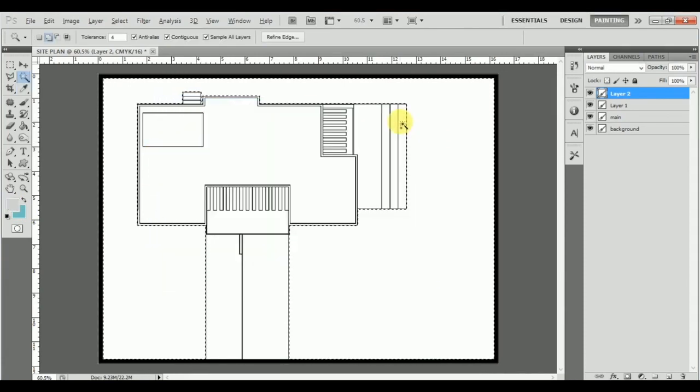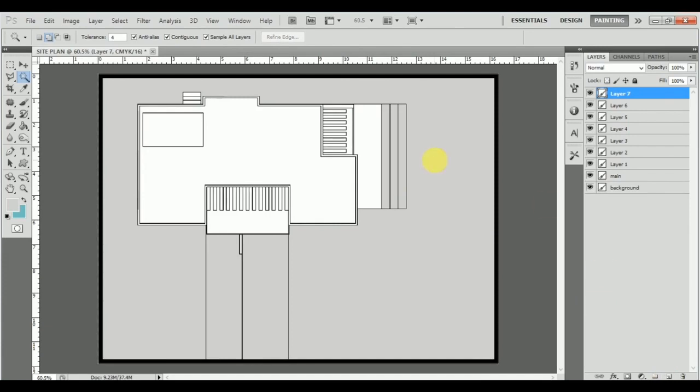Now similarly, like we have created layers in the past, we'll be doing the same thing over here. Each and every particular space will be created and given a layer. We'll also start from the bottommost stair over here, because those two will be in separate layers like this. So we quickly go ahead and fill all these layers up. I hope by now you guys have understood why we create layers, how you use these layers, and what you really do with the layers. Now guys, once we have finished this, I'll go ahead and quickly put up these stairs as well. Do understand you have to finish one staircase at a time, one stair area at a time, like this.